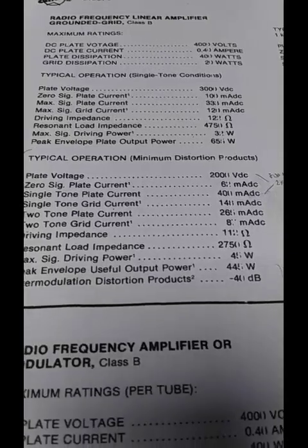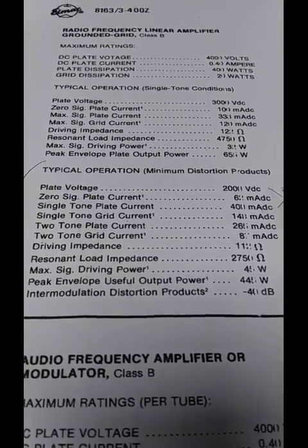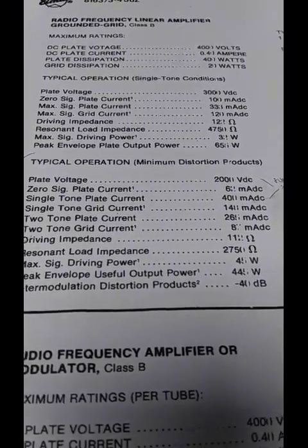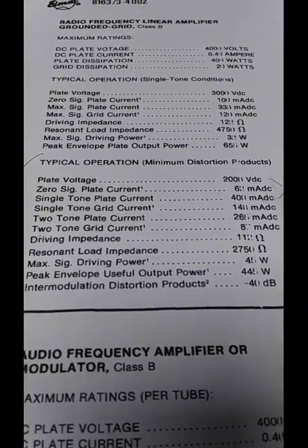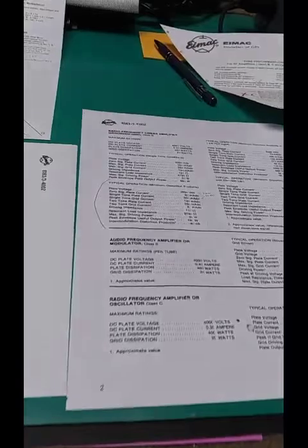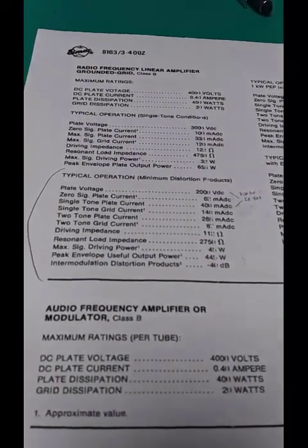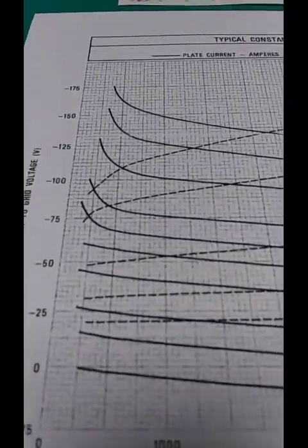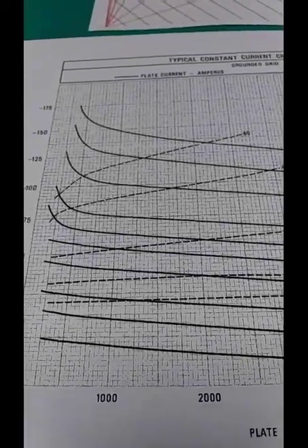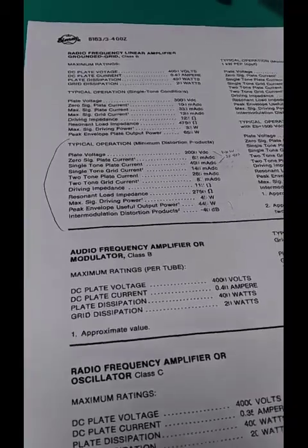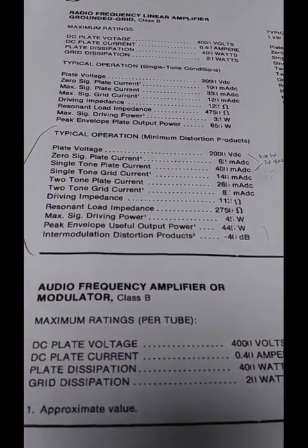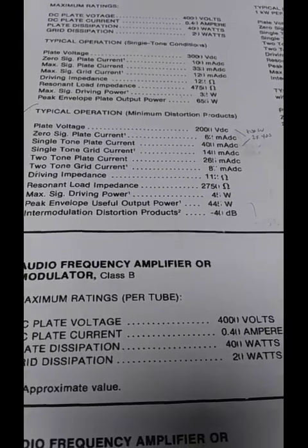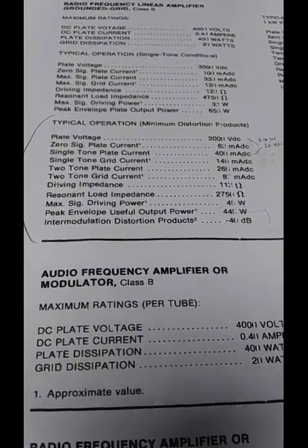And at first glance, it looks like we can take these numbers and go put an amplifier together. Not going to happen. Basically, the only two things on here we can hang our hats on are 2 kV plate voltage max and the load impedance of 2750 ohms. The rest of it is obfuscated. The goal of what I'm doing in completely redesigning an amplifier, and I mean calculations all, is to find a way to transfer this information over to here, and that's not in the books. Somehow the load line that appears on this graph must agree with that information in that case, and it has to, because these are the tube characteristics that become these measured performance characteristics when that tube is put in a test fixture. So it's guaranteed that there's a link between the two. They don't tell us how to get there, and it's complicated.